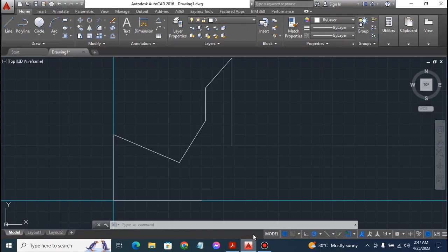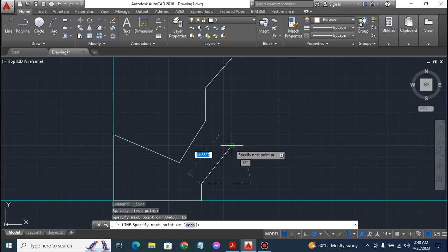So we'll go back to our CAD, click on line. Yes, that is it, like so. Click on line, then lock it to the end of the horizontal line, to our starting point. Then you use the cursor to indicate the direction you want the line to be in. Ensure it's at 90 degrees, and you type in the distance, which is 15, then press enter. Now we have our line at 15. Now I'm not going to exit the command. We want to join this point now down to the end of this vertical line. So we'll do that like so.